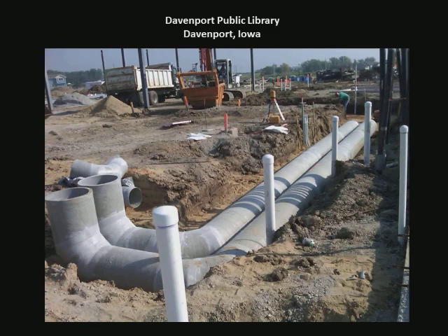Here we have where it's turning up into a mechanical room. Again, because we don't have to worry about corrosion, we don't have a crawl space. That means our mechanical room can be set on grade and the fiberglass ductwork can turn up and attach to sheet metal ductwork once it's risen above the slab.